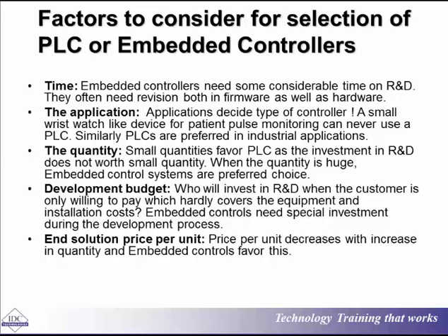So when we are trying to look at deciding on which PLC or embedded controller to use, we tend to look at the reaction time of the process and also the setup times of the actual controllers, including the PLCs.